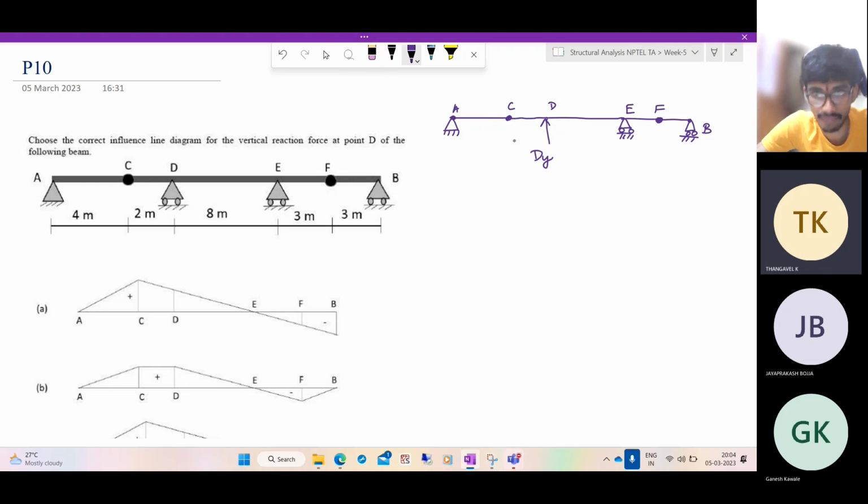So here, when we apply this, the deformed shape will be here. The displacement has to be 0. But there's an upward force. So this hinge can move up, can go like this. And here the displacement has to be 0, definitely, because it's a support. We are not removing the support. So here it's 0, but it continues. It cannot change its shape because it's not an internal hinge. It continues as a straight line. And here there's an internal hinge, so the slope can change. So if you draw the influence line diagram, it will look something like this.